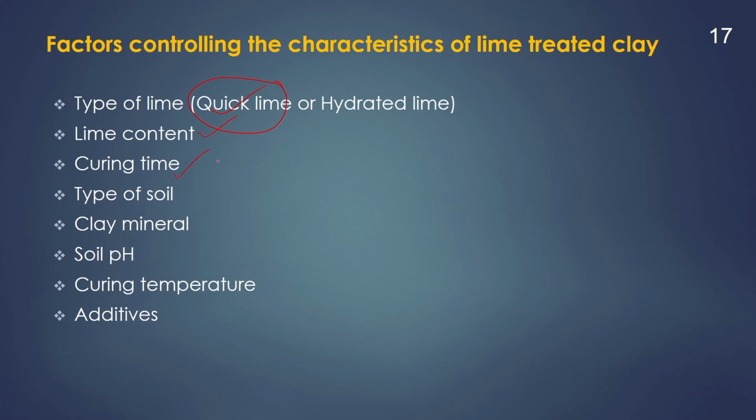Next is the curing time. Curing time is the time which we should give to the soil after adding the lime for curing. With an increase in the curing time, the strength of the soil will increase.